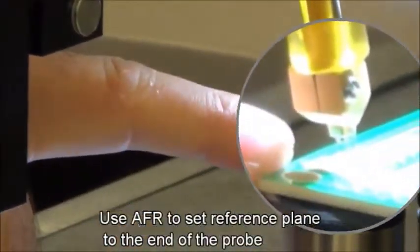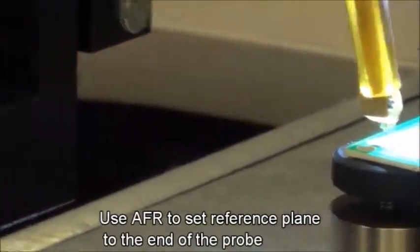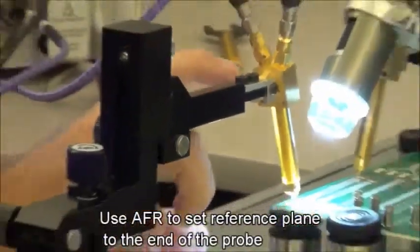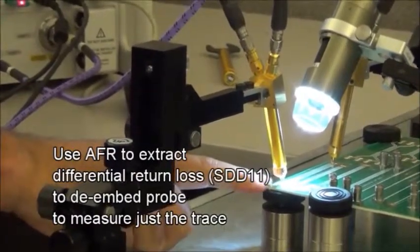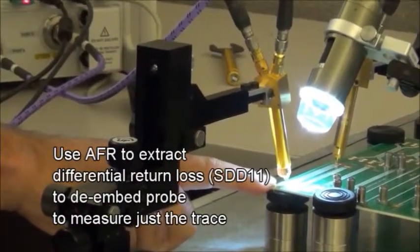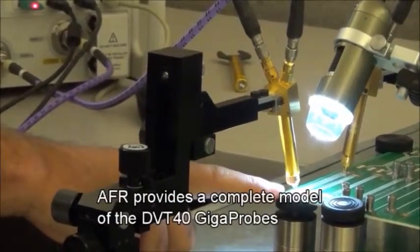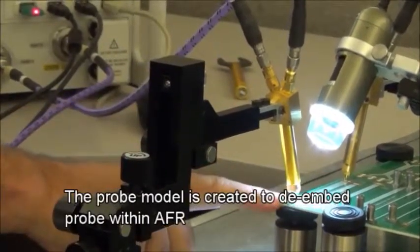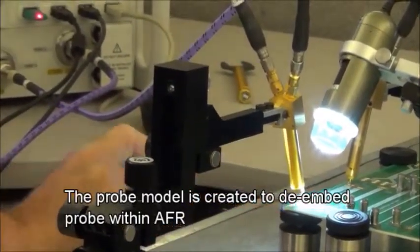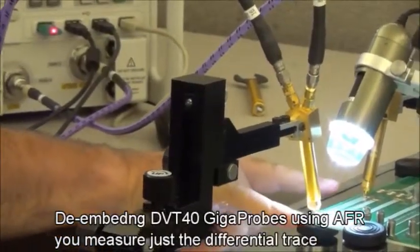Here, we're going to actually use AFR. We're going to derive the S parameter model of the probe by using an SDD11 measurement. With that one reflect measurement, we're able to get the complete model of this probe and then de-embed that inside AFR and get just the measurement of the trace. So let's show how that happens.